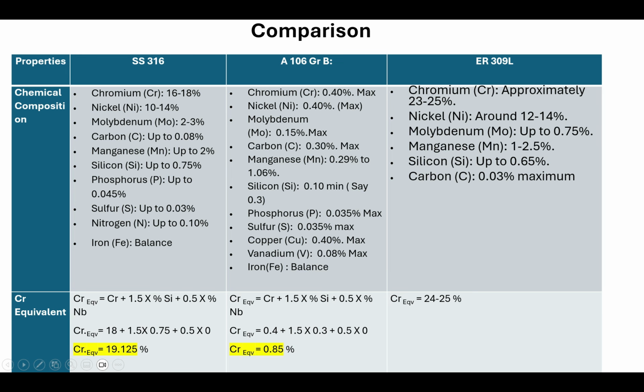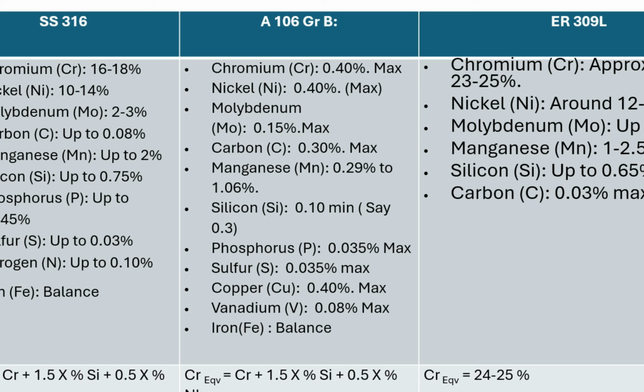See, the carbon percentage is kept extremely low because from the carbon steel side there will be some contribution which will give a higher percentage of carbon in the final weld deposit. Therefore, you have to balance with an extremely low percentage of carbon in the electrode or the filler. So this gives you a chromium equivalent of say 25%. We can also calculate the nickel equivalent.